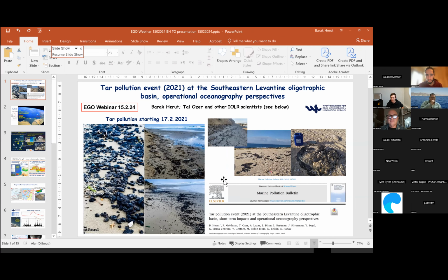Immediately getting this location, we ran the MEDSLIC, which is coupled with the other hydrodynamic models, a forward simulation of the propagation of the slick from this 11A location. Actually, it coincides in terms of location of the tar landing and the timing to the occurrence of the tar. We also did some backward trajectory to get the first estimate of the source of this oil pollution.